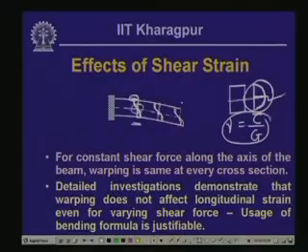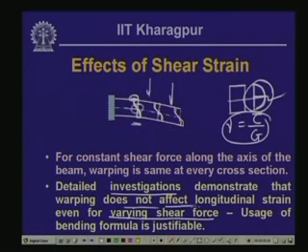Also, it has been observed that when we go for a detailed investigation of such warping because of non-uniform shearing stress, that means if the shear force is not uniform along the beam, if there is varying shear force, then the warping will not be constant in all cross sections, and thereby there will be some amount of change in the longitudinal strain.